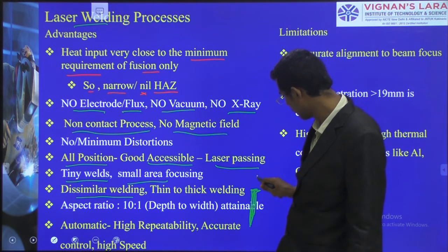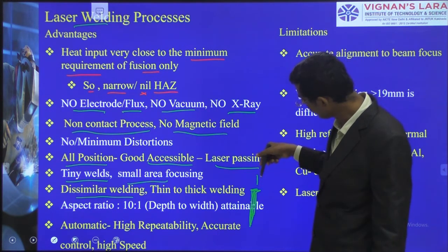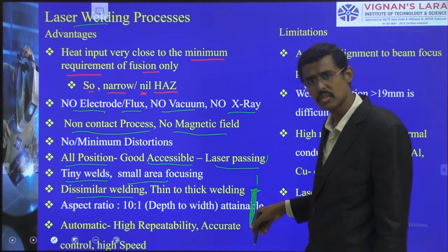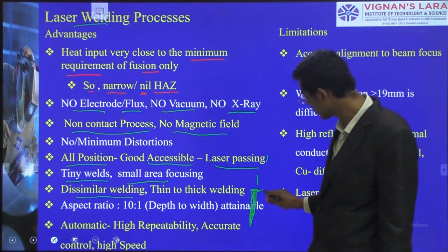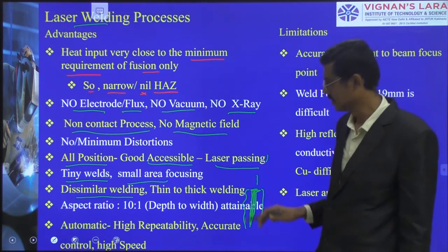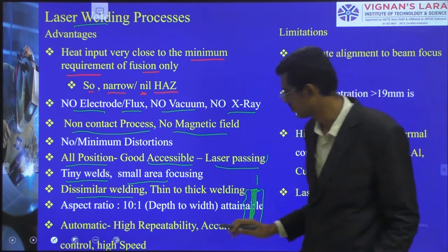Small intensified heat is supplied here, and we go deep doing the penetration, to the thickness we need. We have no need of these heat affected zones. Therefore, the depth to width aspect ratio is very good.